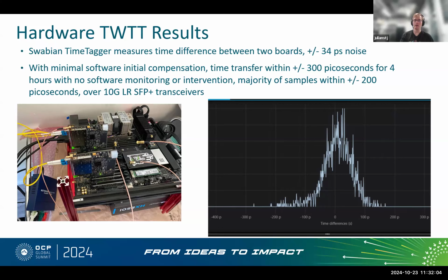time transfer range. And I should note that there's a lot more optimization that's capable with these DPLLs. I didn't play much with, say, the loop filters, loop bandwidth, all of the more complex features of a DPLL. They're a little outside of my scope, but Greg and his team, I'm sure, could get this performance to be much stabler and cleaner, given time to optimize your loop parameters.